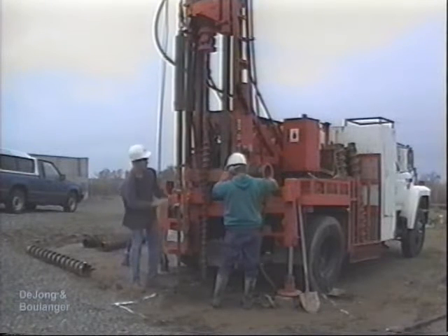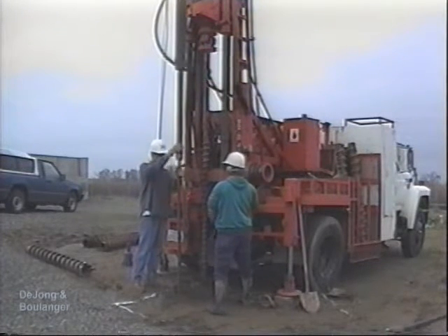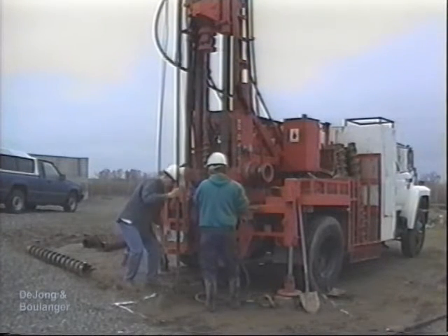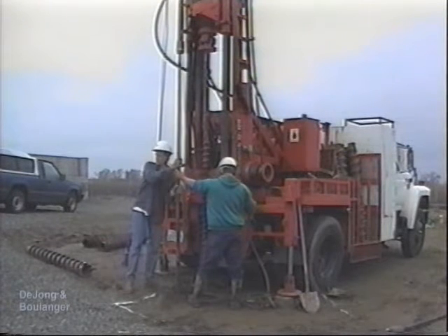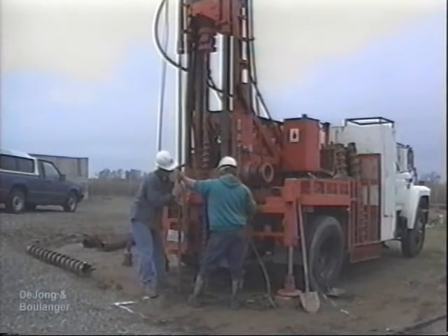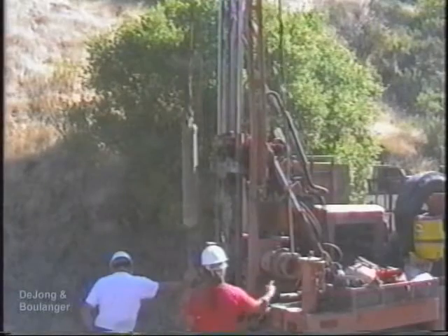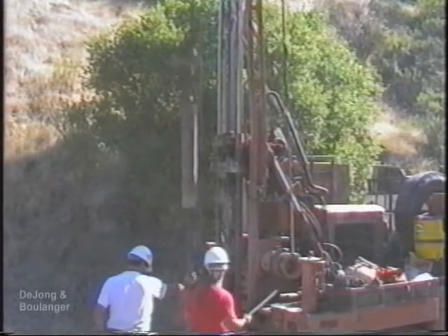The blow count rate, or number of times the hammer is dropped per minute, can also affect the N value. During sampler penetration, negative or positive pore pressures may develop in the soil. A low rate of blows will permit more of the excess pore water pressure to dissipate between each blow than can occur with a faster blow rate. The result is different effective stresses and thus different N values. A rate of 30 to 40 blows per minute has been recommended.